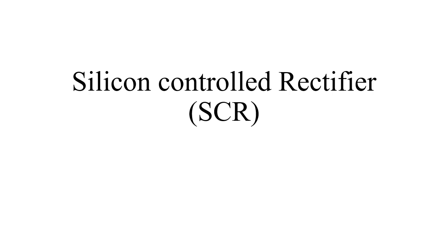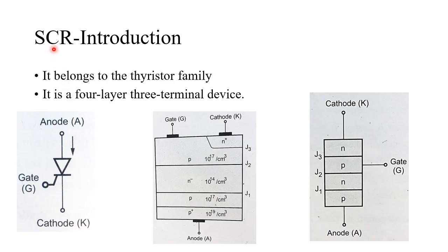In this video, we are going to discuss the silicon controlled rectifier, that is SCR. SCR belongs to the thyristor family. It is a 4-layer, 3-terminal device. The 4 layers are P, N, P, N, and the 3 terminals are anode, cathode and gate.